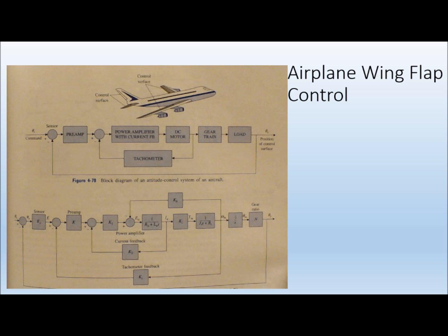If you go down to the bottom block diagram, the more in-depth one, you start on the left with your input signal, and then the first three blocks would be your controllers, and the next three would be our model of our motor and how it affects our system. We have a few feedback loops after the motor. The one on top would be our back EMF from your motor. The one on the bottom would be the tachometer, that KT. Then to the right is another model of our load, and then another control feedback loop back to the input.